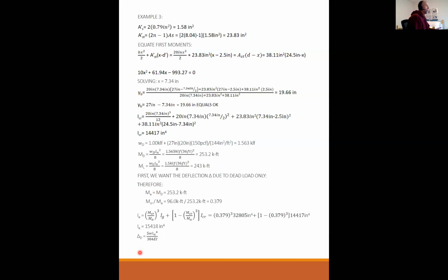And so slabs cover an area. They go from here to there and from over here to over there. Slabs are designed as pounds per square foot. Normally in everyday design you design your slabs first, and your slabs are spanning from beam to beam. So when you design your slabs, you're designing with pounds per square foot. But when you take the tributary area of your slabs, then the loads to your beams are pounds per square foot times the tributary width. That gives you pounds per lineal foot or kips per lineal foot.